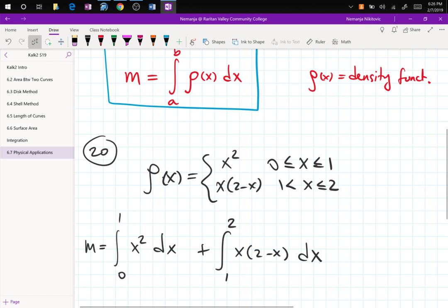As you draw current through them, one will heat more than the other and it will bend and open the circuit. Cool design, right? And then what do people do? Oh my God, my circuit breaker constantly pops out. So let me take the 20 amp out and put in a 30 or 40, and then they wonder why the house burned down.